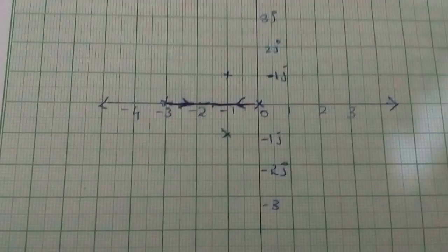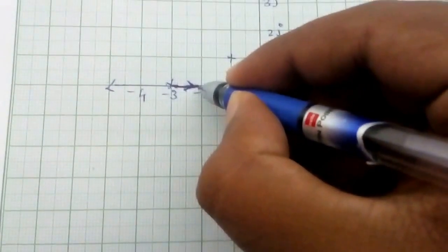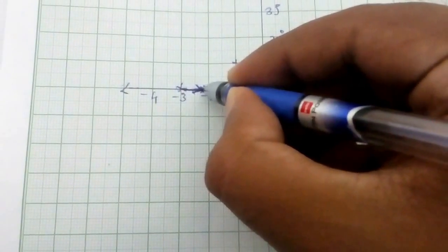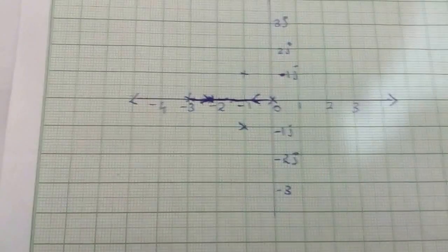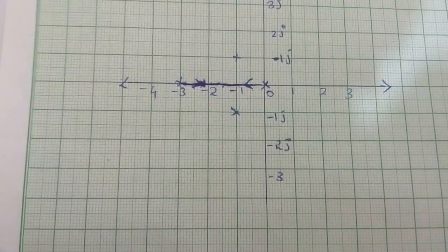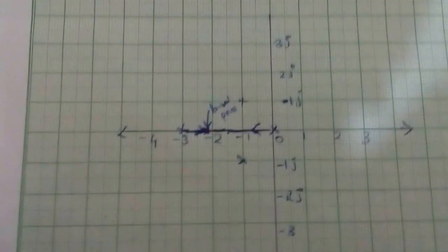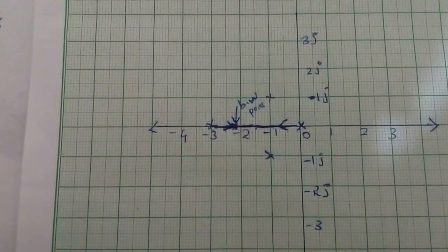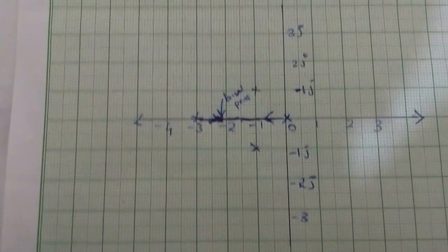negative real axis. First of all, mark the breakaway point here, that is minus 2.28. It will be something right here. Sorry, but it's a little bit dirty. I'm sorry about that. It will be minus 2.28 on the breakaway point. So, that's the breakaway point. And as I said earlier, we need to find the direction of this movement of the poles from the breakaway point.